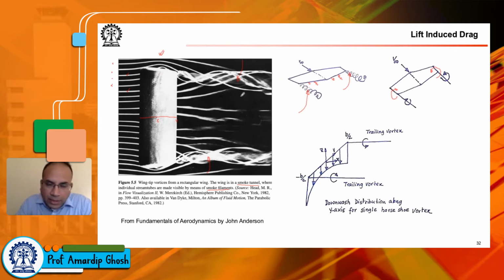And I saw for the first time how beautifully these vortices on a delta wing are being generated and demonstrated. Water tunnel, colored dye, delta wing at an angle of attack. You have these very strong vortices on the upper surface of the wing, and it's a very strong tool to understand flow fields, and as I said, to get the phenomenological description of things, because only once you are clear about the phenomenological description, you can apply analysis and get somewhere.